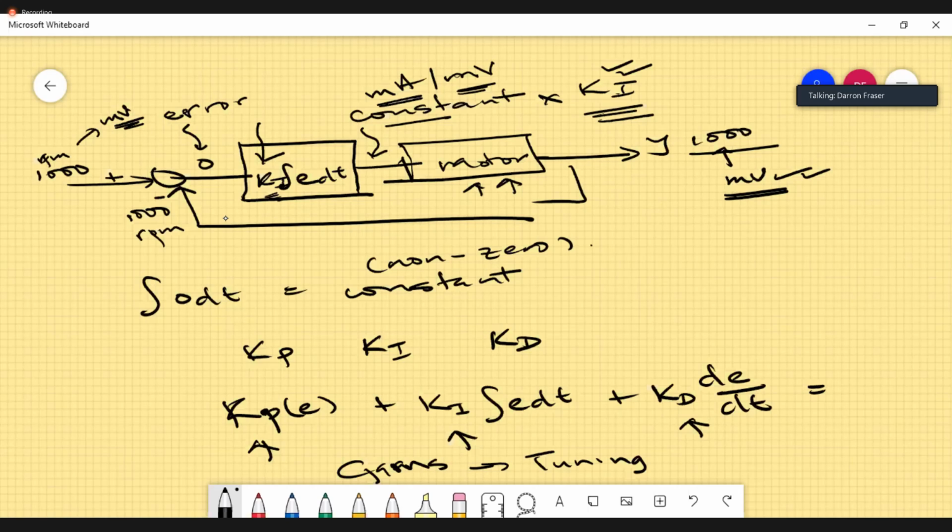There's no system currently that I know of in Jamaica or most parts of the world where they know the transfer function. Because most engineers can't be bothered to work out a transfer function. And so they just resort to PID control and just use that. So pole placement is nice and it gives you better things and all those types of things, but you have to know the transfer function of the system to use pole placement at all. So this is the go-to method for all industries.